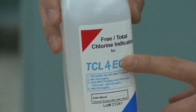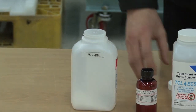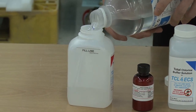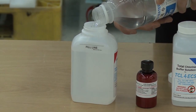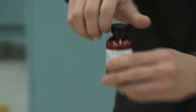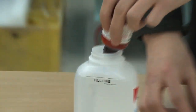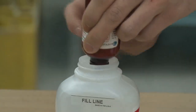Step 2. Chlorine indicator reagent is installed on the left side of TRO sensor. 1. Fill the bottle 3/4 full with distilled water. 2. Add DPD powder and pour the distilled water to the line. 3. Close the cap and mix thoroughly.